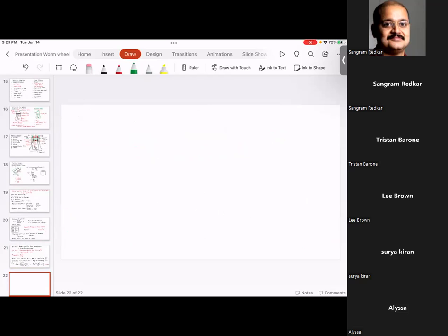So let me give you an expression for indicated power. Indicated power, also denoted as IP, is P M L A N divided by 60, where L is the stroke length, which is the length of the cylinder, and A is the area.